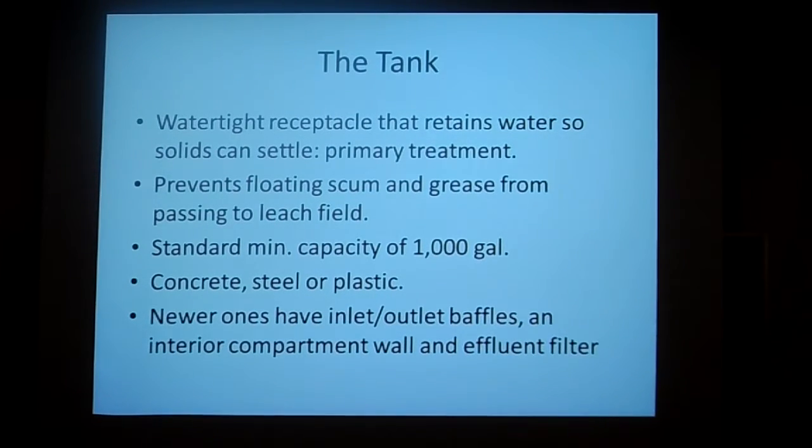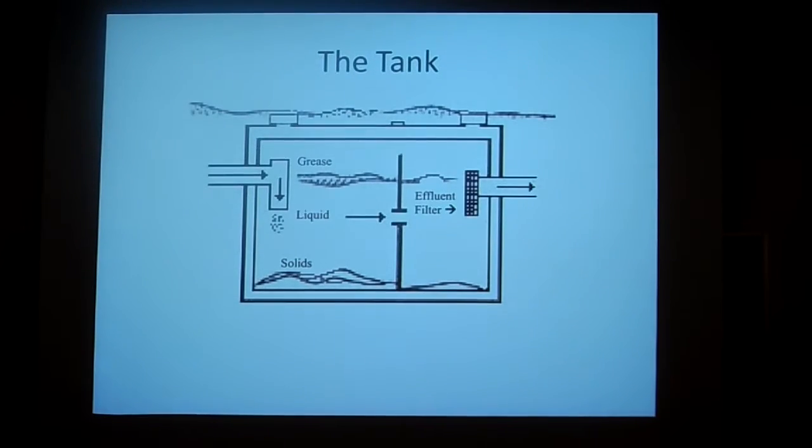The standard minimum capacity is 1,000 gallons. They're constructed of concrete, steel, or plastic, and newer ones have an inlet and outlet baffle, an interior compartment wall, and an effluent filter, which you can see here.